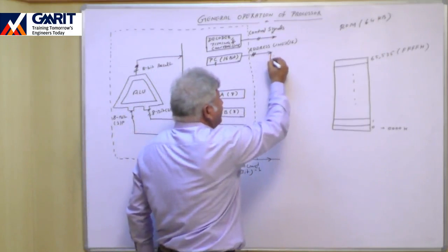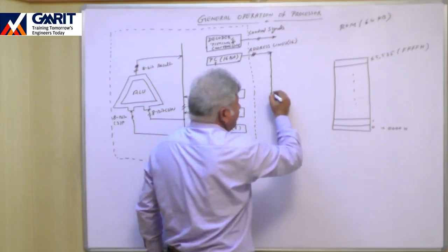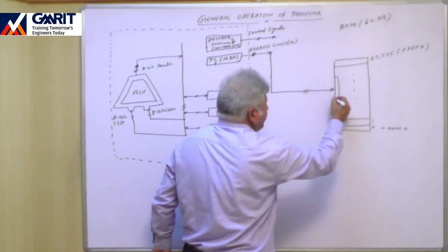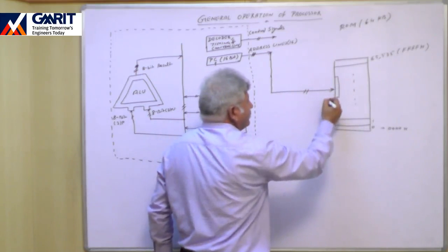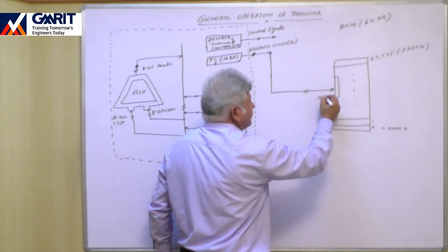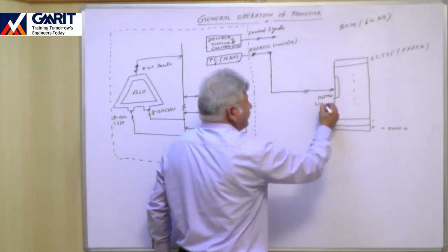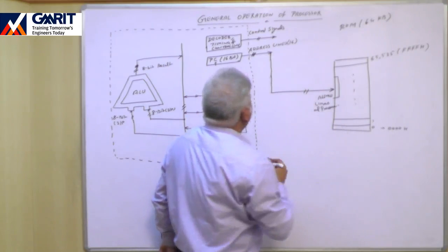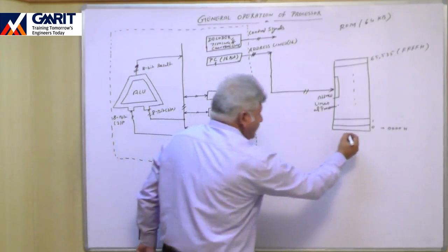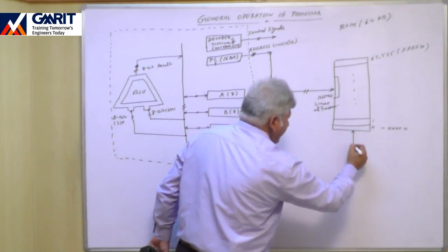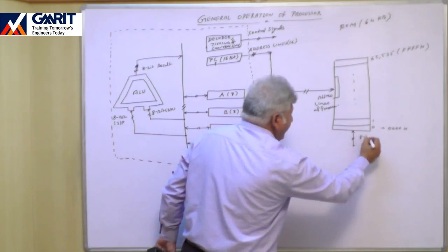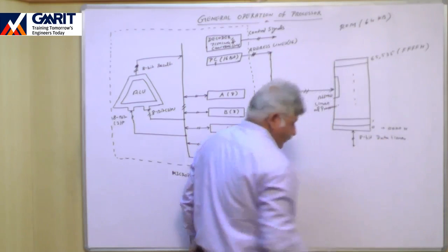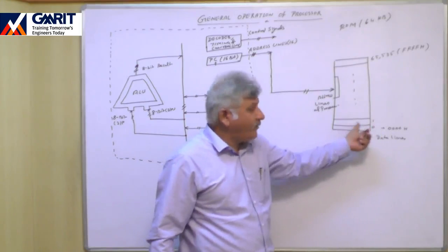Now these address lines will be connected to the address lines of the processor, and this memory has an 8-bit data line, because at each location we can store 8 bits of data.